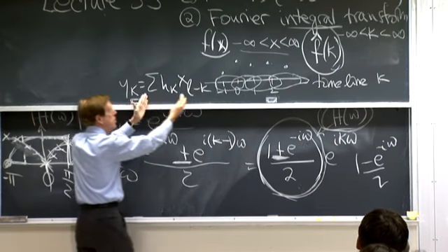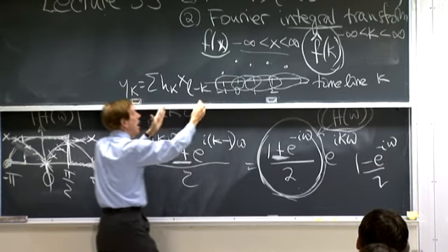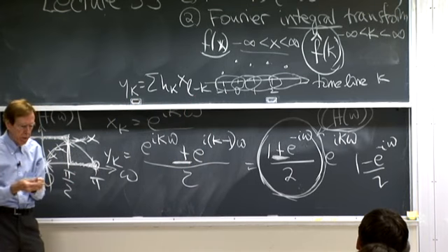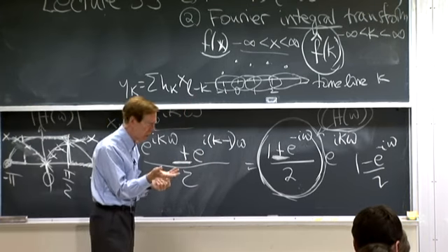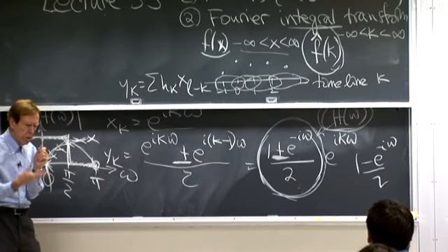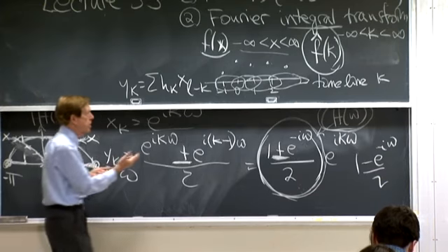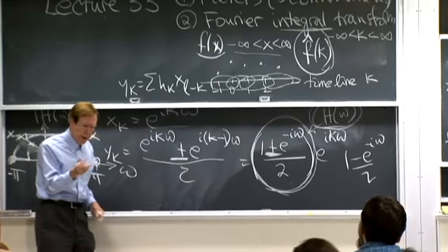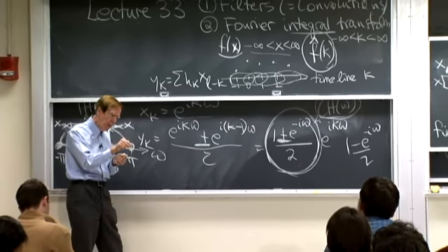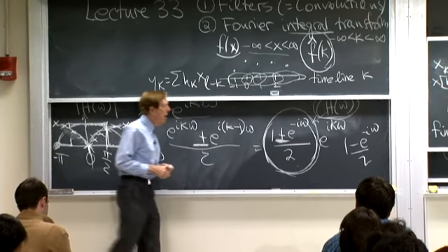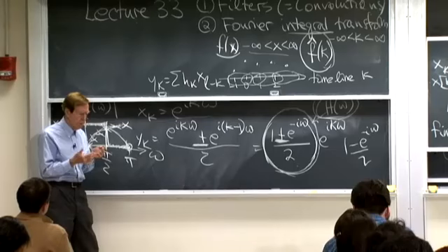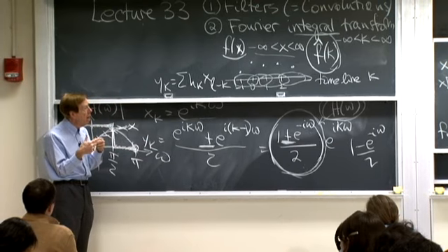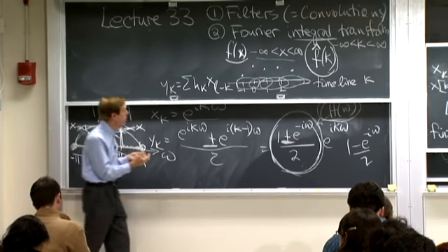So the window is the width of the h's, and as that window moves along, you could design a little circuit that would do exactly this, that would do the convolution. You just have to put together some multipliers, because you have these h's, and you have to put in an adder that'll add the pieces. And so those are the essential little electronic pieces of an actual filter.